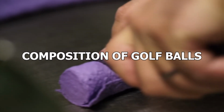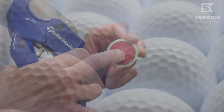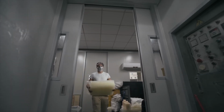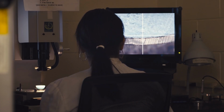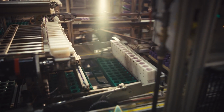Composition of golf balls. Two-piece balls comprise a solid rubber core with a thermoplastic ionomer resin cover. The rubber starts as a hard block, which is heated and molded into a sphere. Three-piece balls consist of a smaller solid rubber or liquid-filled center surrounded by rubber thread wound under tension and covered with ionomer or balata rubber.